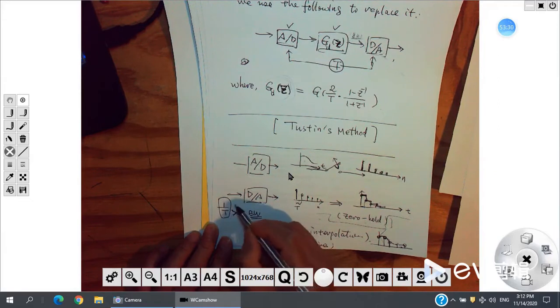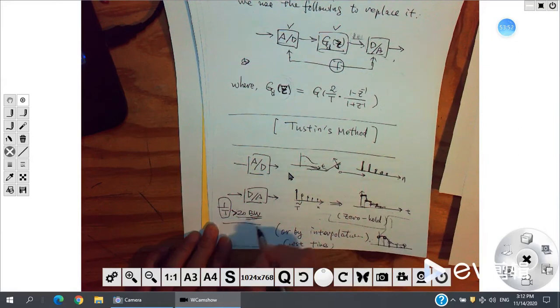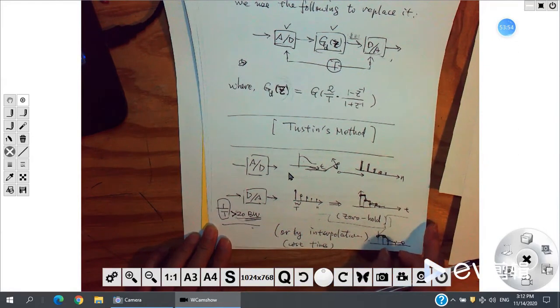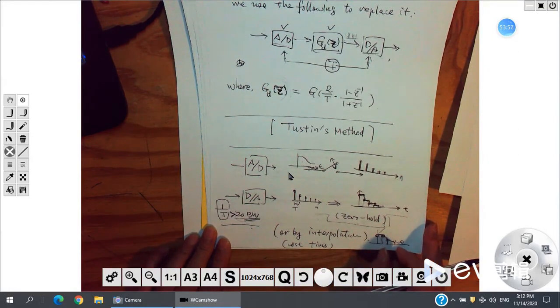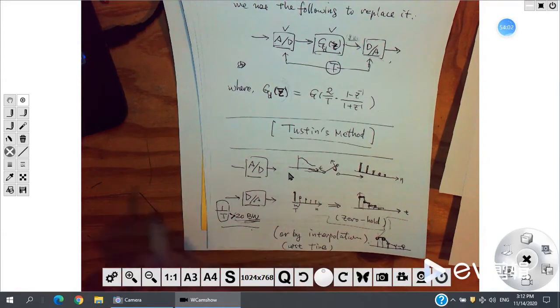That means every second you need more samples. The sample rate is larger than 20 times the bandwidth. Then the error will be small. You still have error, but this error is fine. You don't think this error will give you some big mistake, right? Okay, so this is the testing method. Then we can check an example.